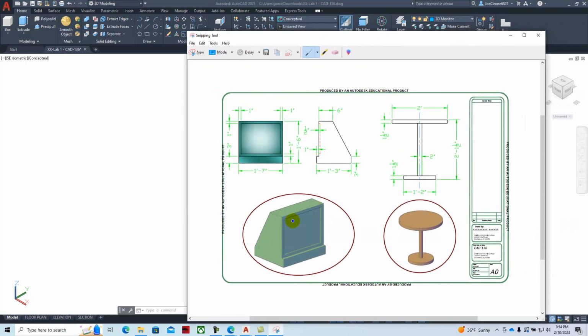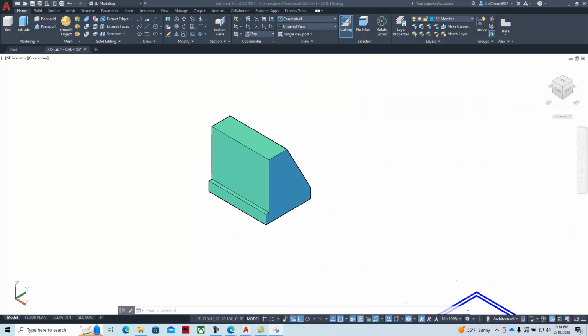To create the computer monitor indent part right here, I'm going to put a 3-point UCS in the front of this. And then I'm going to create a rectangle around the outside of it. And I'm going to offset that 1/2 inch. So here's my 3-point UCS.